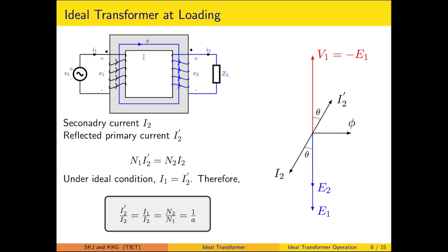However, the flux level has to be maintained, that is a property of the magnetic material, so the primary will continue to draw current. Whatever decrease in the flux arises because of the N2I2 MMF will be counterbalanced by the increase in the MMF, which is N1I1.